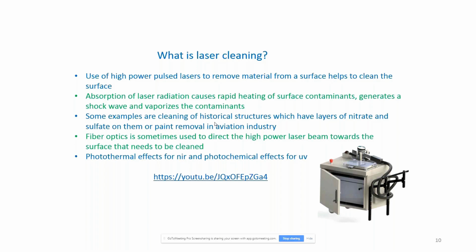So absorption of laser radiation causes rapid heating of surface contaminants and generates a shock wave and vaporizes the contaminants. Some examples are historical structures and removal of paint in aviation industry, which we'll go in detail later.